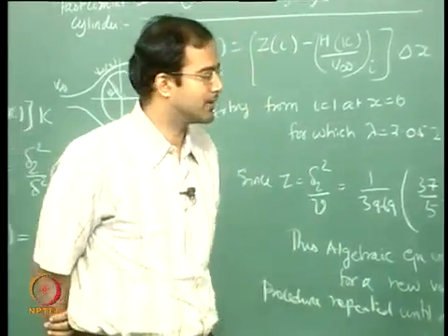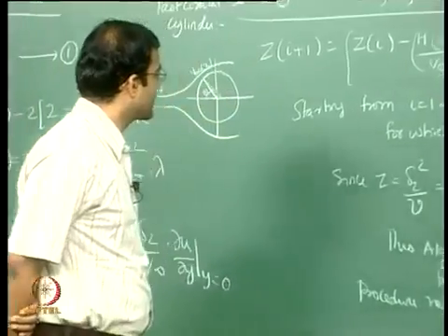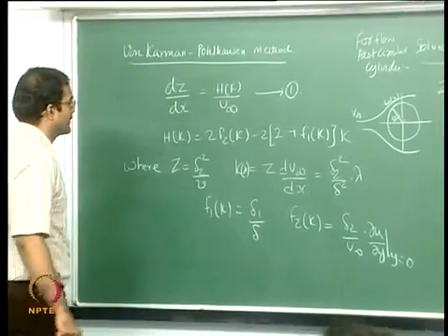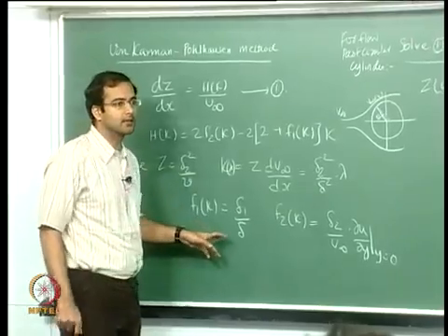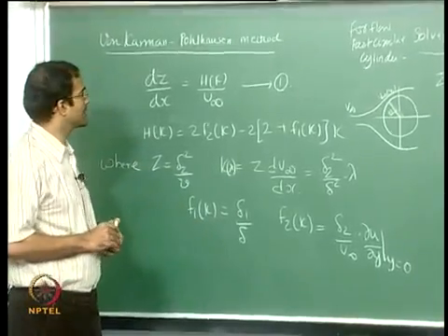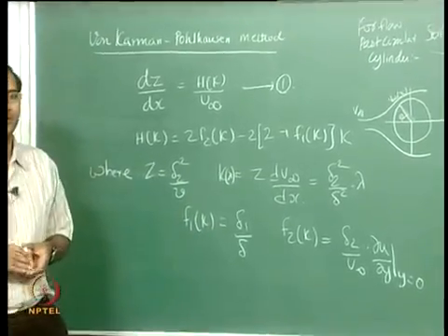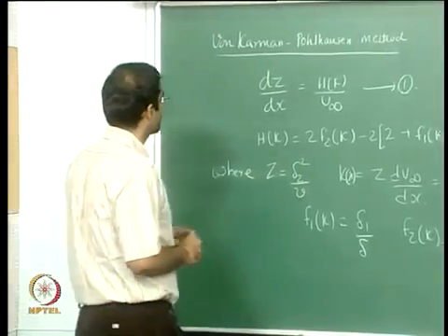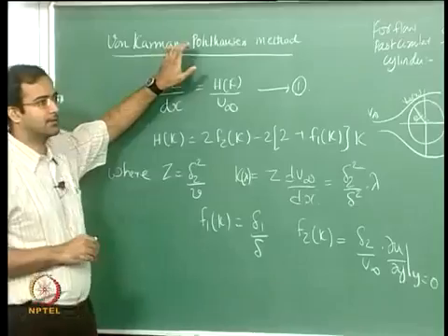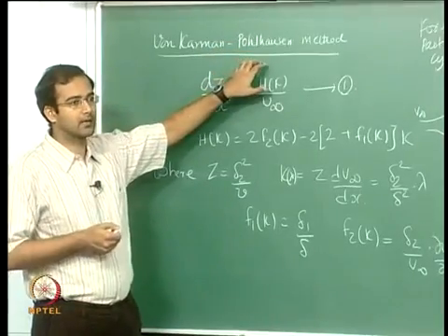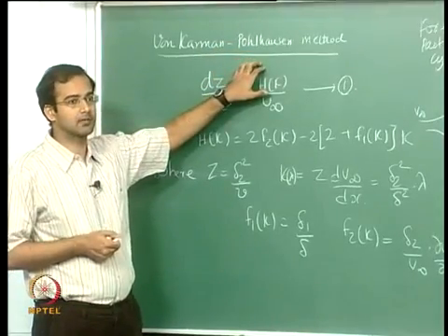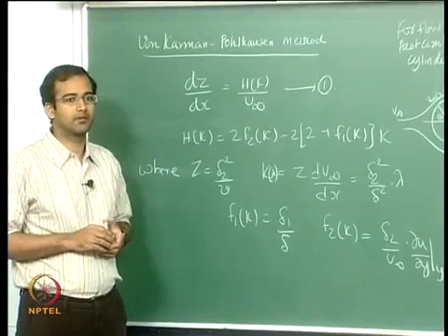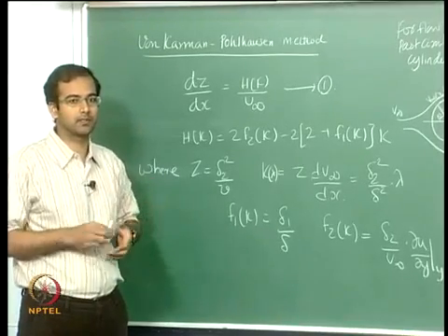So yesterday we were looking at application of the approximate method to flows with pressure gradient. This method is also called the von Karman-Pohlhausen technique, which was originally conceived by von Karman. He suggested that we can use higher order polynomials and substitute them into the momentum integral equation to find solutions for flows including pressure gradient.